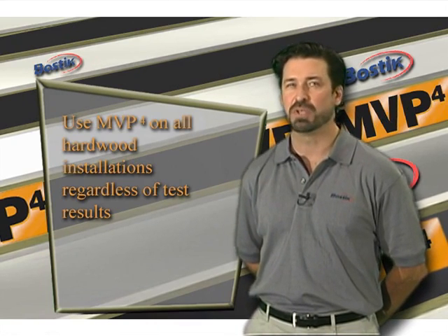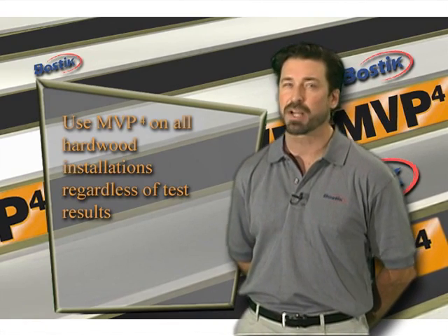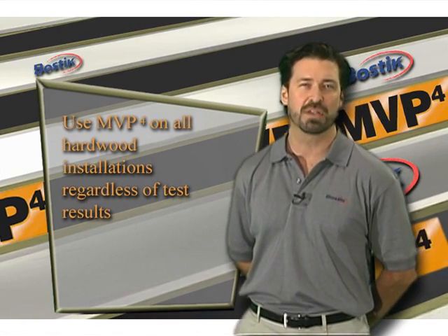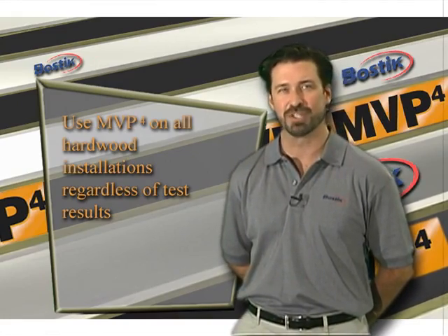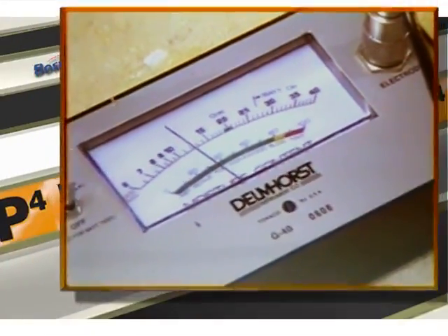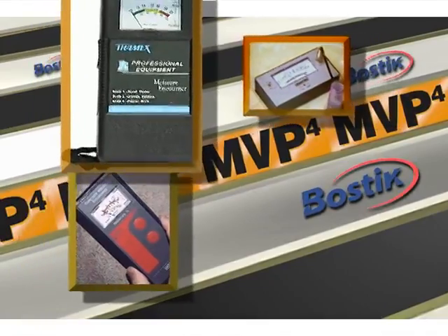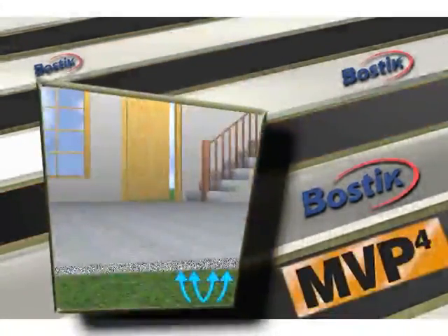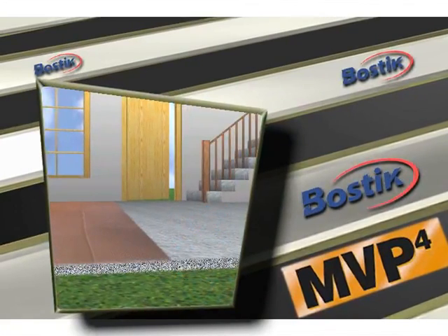We recommend that this be done regardless of whether the results of the wood flooring manufacturer's recommended moisture tests are within or exceed their acceptable limit during the installation. Here's the reason why. A subfloor moisture test performed today, which produces an acceptable reading prior to your flooring being installed, isn't a guarantee that your wood flooring won't be affected by future moisture vapor transmission. But with the proper use of MVP4 per the product datasheet, you'll have a warranty for protection.